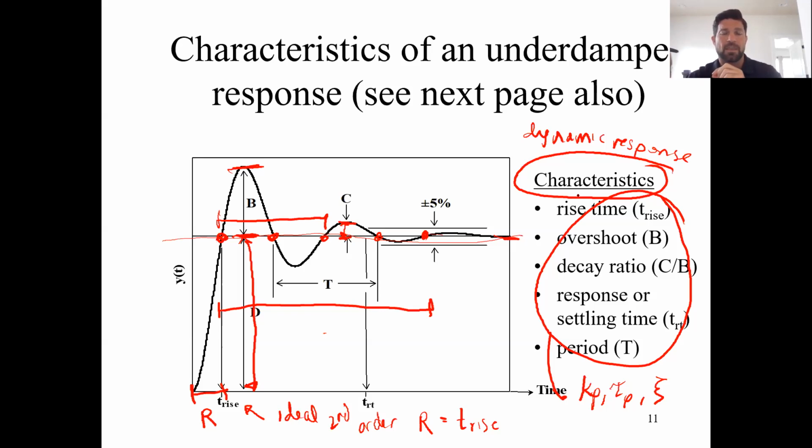You have your dead time, and then you apply all the characteristics of the second order after the dead time. If you're given process data that might look like this, you don't necessarily know what is going into it. So what you have to do is assume that it has a dead time. Given process data, you have to assume that it has dead time.